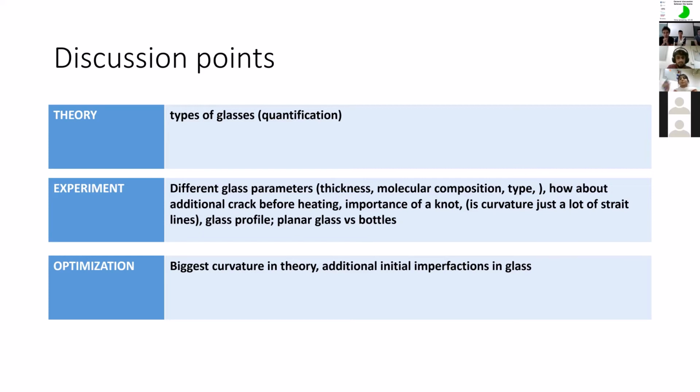Okay. The thing is that a crystal structure might not have been able to build a temperature gradient, basically. So we would not have gotten the fracture because of the uneven expansion and contraction in the glass. That is why we get that localized heat. In a crystal, the heat travels uniformly, and the whole thing would have been heated. Even if we put it in water, we wouldn't have gotten a fracture because there wasn't this uneven expansion and contraction. So there wouldn't have been any thermal shock or temperature difference. It is this property of glass to fracture under thermal shock. I hope that answers your question. Okay, thank you. And if you have any ambiguities, please do ask again.